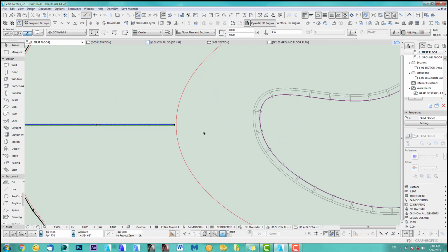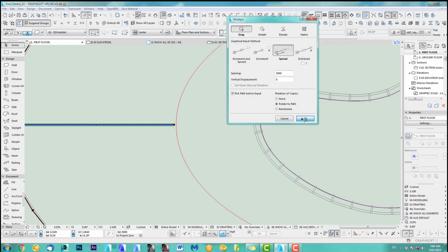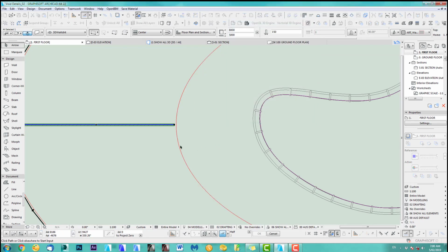As you can see, it's not too happy, and it comes down again to the magic wand tool setting. I'll show you. If I do this again, yeah, see now, it depends where you go. See, it doesn't pick. It picks where the polygon touches the ellipse. So this is not smooth enough. I can see this is not smooth enough. So we have to go and change the magic wand tool.